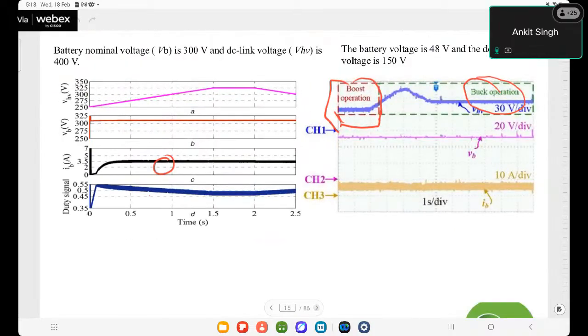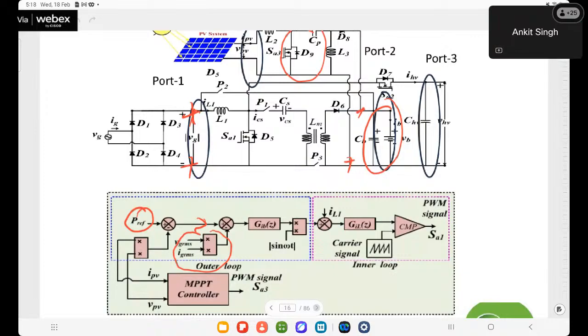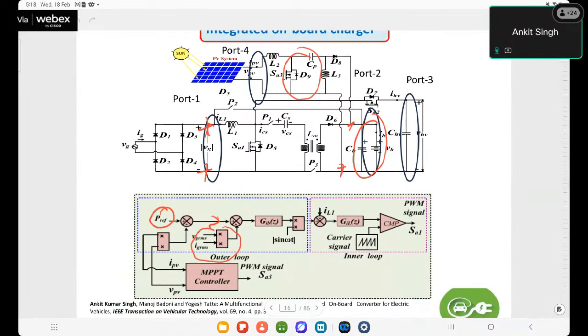We use the single stage system because when we talk about onboard applications, it is important that charger size and weight stay light. So people prefer the single stage system. In a compromised way, we can increase the filter to some extent, so that it does not increase the ripple much.